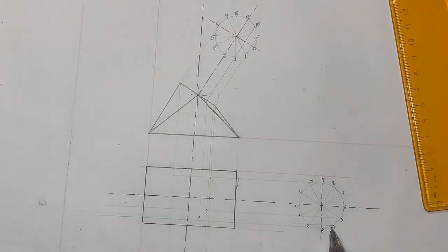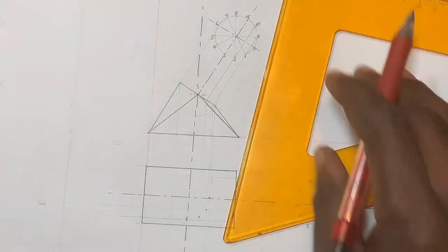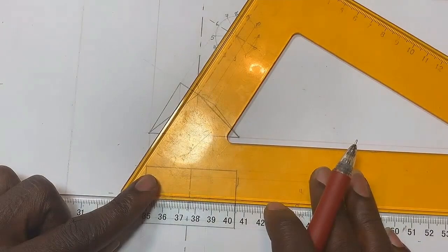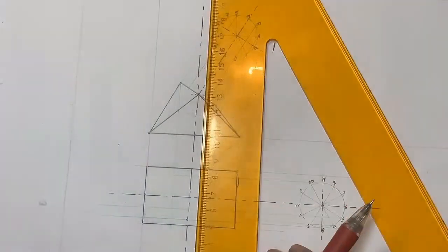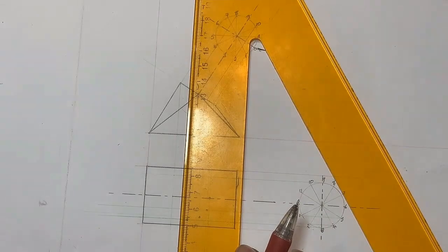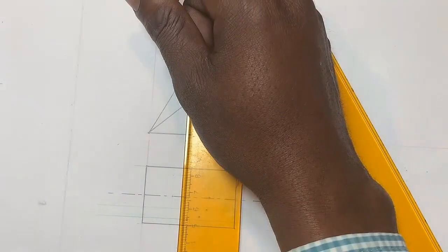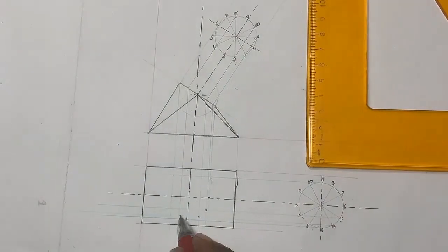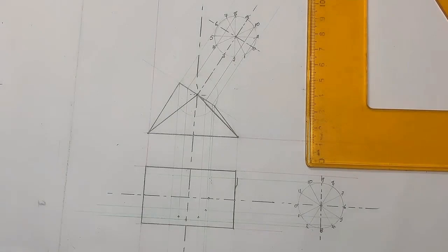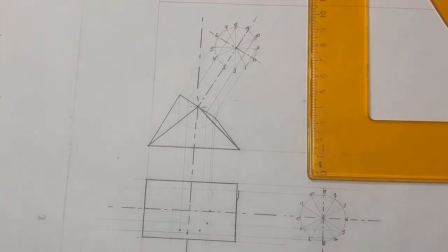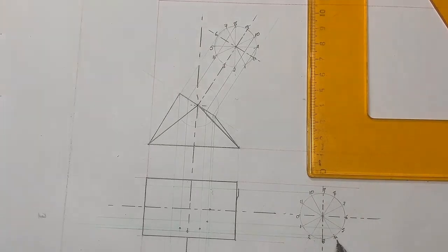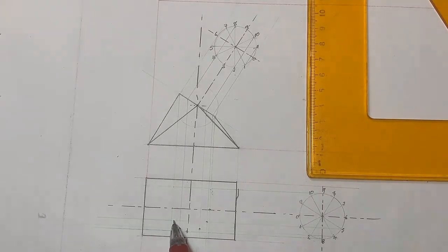Then point 4, we've already dealt with it, which we said is in the same line with what? With 2 angle. But off your auxiliary front, you've even constructed it, which is in the same line with 8. There you go. Once I touch the inclined line at an angle of 30 degrees, then you go vertically down. So I'm having a point right here. Everyone. Then after that, what is going to happen? After that, we go to 5. 5 is in line with 1, which means I must be getting 5 this side.